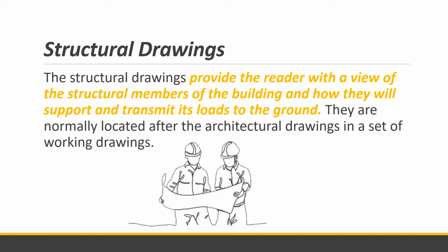So usually mauuna is yung sa ground. So sa actual construction, magsisimula ka from the ground. So you will dig the ground and then mag-start ka sa footing, yung column, then tie beam, and then yung continuation ng column, and then beam, and then yung slab. Or column, roof, beam, for example, sa one-story building.